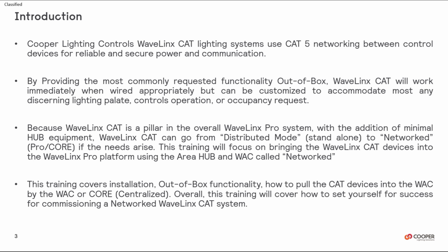This training will focus on bringing the WaveLinx CAT devices into the WaveLinx PRO platform using the Area HUB and WAC. We'll call this networked. This training covers installation, out-of-box functionality, how to pull the CAT devices into the WAC. Overall, this training will cover how to set yourself up for success for commissioning a networked WaveLinx CAT system.